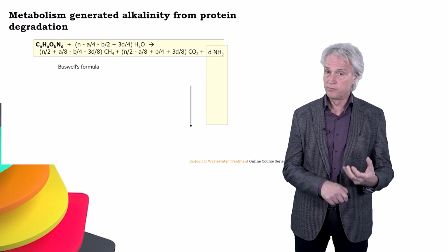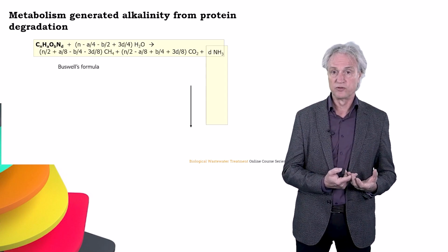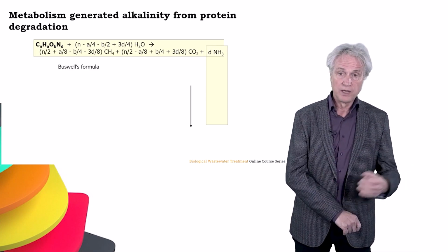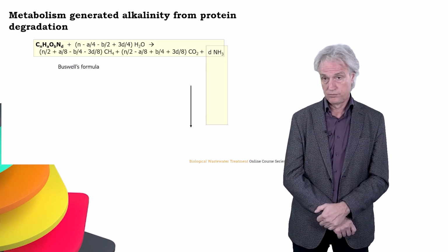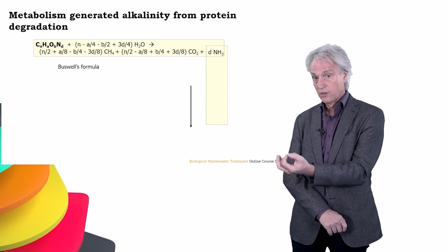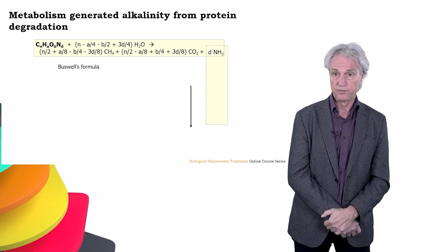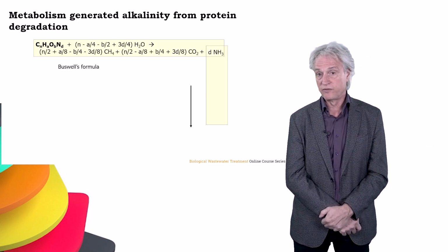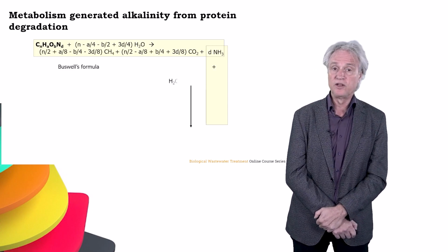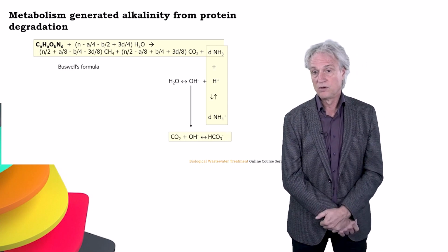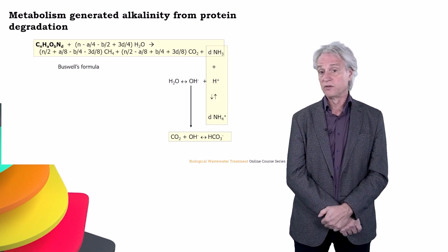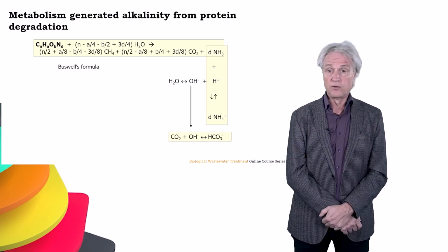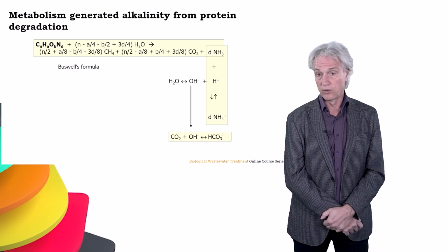Now there are other buffers generated during the anaerobic conversion. I informed you about the conversion of proteins. And the proteins have ammonium. And this ammonium will also be liberated during the anaerobic conversion. Now the pH is 7, 7.5, 8. And under these pH conditions, ammonia takes up a proton and forms NH4.